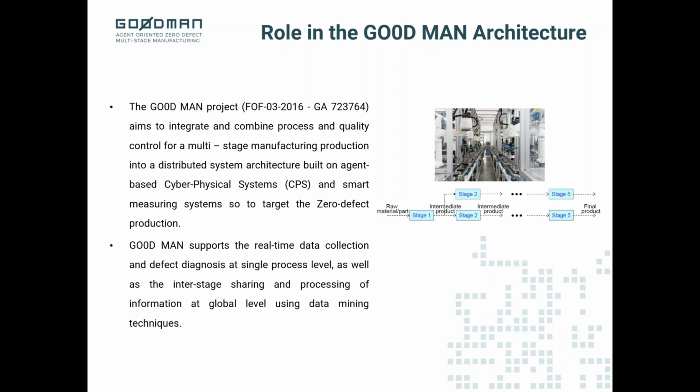And in this case, this enabled the entire manufacturing system to perform early detection of process deviation and self-adaptation to varying conditions. In this context, it becomes clear that a zero-defect strategy requires reliable information to support any decision. Of course, reliable information requires measured data from the process and the product. But in a real production scenario, availability of data does not by itself guarantee an effective information build-up. In particular, measurement uncertainty must be known, kept under control, and adequately managed, so to keep the confidence level on measured data at the required level.